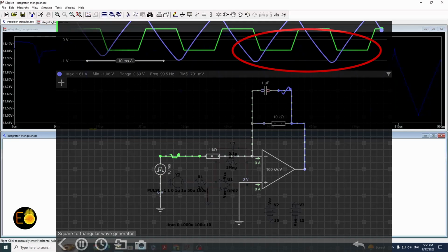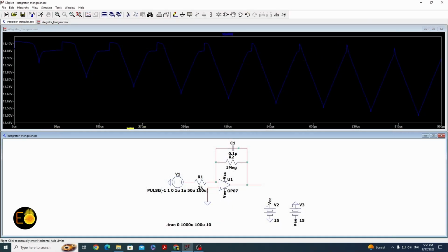So why can't we see it? Because as you can see, the time axis is of the order of microseconds. Whereas if you place a resistor of the order of mega ohms, then in order to reach the steady state you need a time frame of the order of seconds. During physical simulation in the laboratory, you may not observe this transient state because microsecond and millisecond orders of time appear very momentary to us. So that's why we may not see such a transient state.